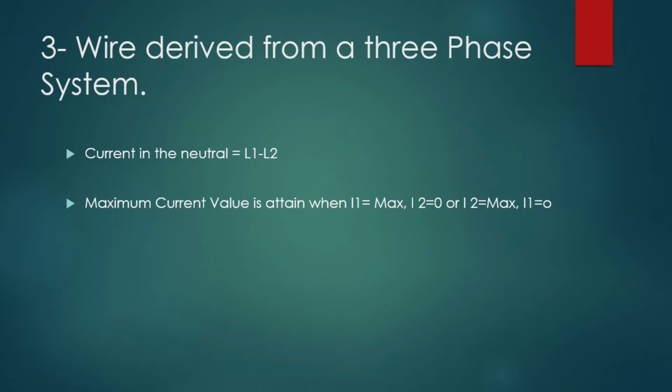All right. So the maximum amount of current that is derived from a neutral is when one of the lines is faulted and the current returning back to that neutral is at max. So the conductor for the neutral should be able to withstand the return current.